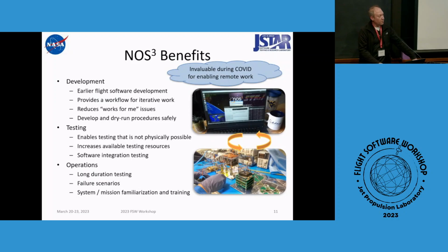On our CubeSat, we had one component that took well over a year lead time. I know this is not a problem that's unique to our CubeSat. This is unique to the industry. We were able to develop the software for that component long before we had it, because we had the spec sheet. We generally knew how it behaved. So we wrote a model for it, and then we developed the flight software to go along with it.